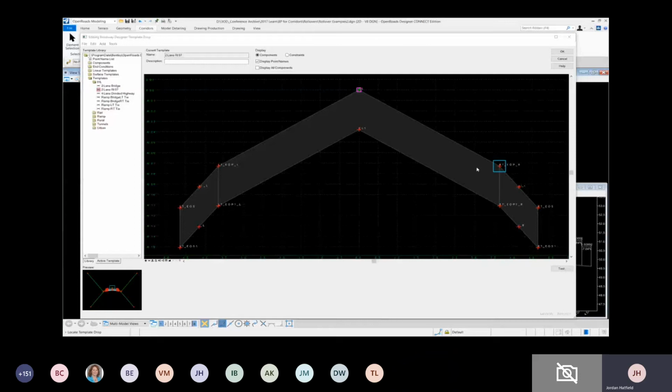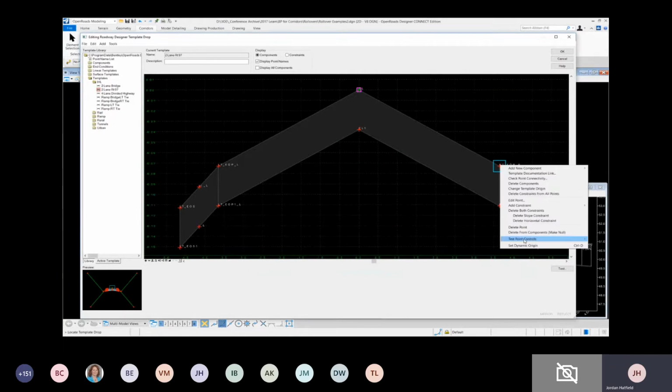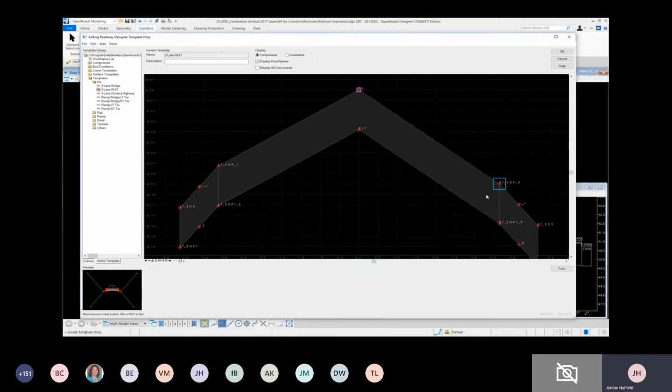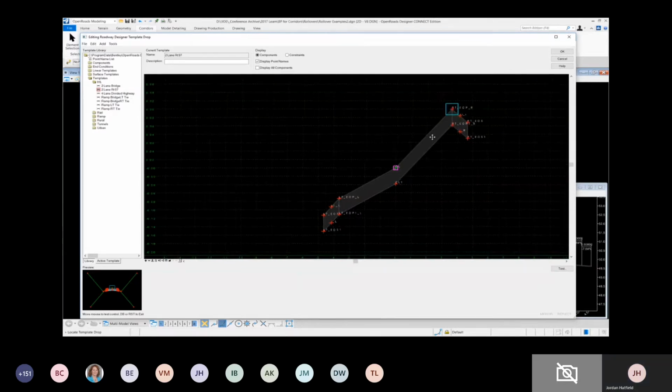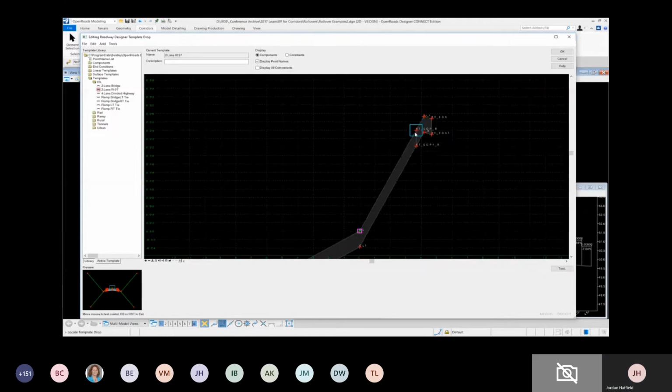Okay, in this example, we have the more complex example shown in the previous PowerPoint. You can see that we have a shoulder PI. So if I go to test vertical point controls, you can see that when we go to the low side, it locks. And as we go to the high side, once we get over 6%, the shoulder PI jumps out, and it locks to be planar with the road slope. And then the shoulder is then 1%.